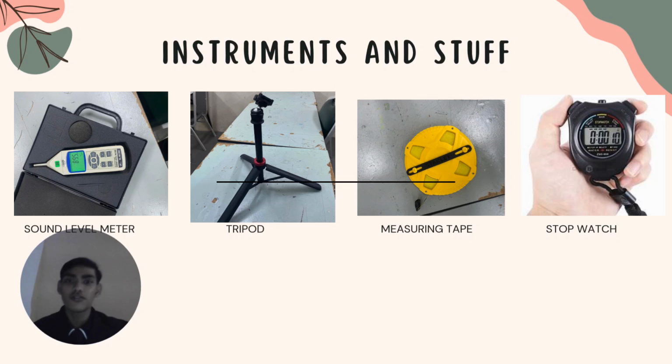Okay, now let's go to the instruments that we used in our case study. First of all, we have a sound level meter, and second, we have a tripod, measuring tape, and stopwatch. In the sound level test, a sound level meter is used to detect sound waves using a built-in microphone, which then converts those sound waves into an electrical signal. This meter measures the sound pressure level in decibels, or dB, to determine the intensity of noise in the environment.